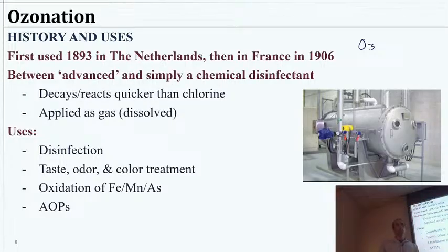It's also good for removing taste and odor, things like that. So you may have seen it before. You can actually get aerosolized cans of it as an industrial deodorizer, to just kind of wipe out any gross smells. You can use it for color treatment. Talked about the fact that some people like drinking brown water, but you usually don't like brown water coming out of your tap, right? So if you had a bit of tannins or something giving your water some color, and you obviously know that your consumers aren't going to like that, maybe you can use some ozone and clean that up.